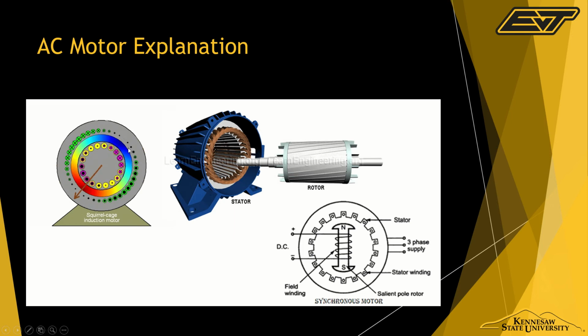And how it works is that you have a spinning magnetic field that's made by these coils. And generally, those coils are interwoven together a lot. Typically, each coil will span 120 degrees over the motor. So this coil connects to probably that coil, and then the next one would connect to the one after that. And the reason why they're so overwound next to each other is so that you can get a very, very even magnetic field that spins.